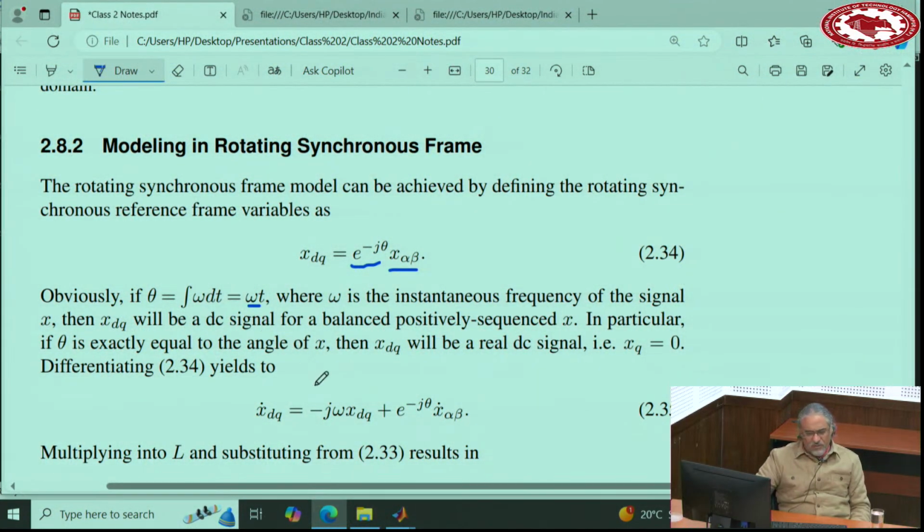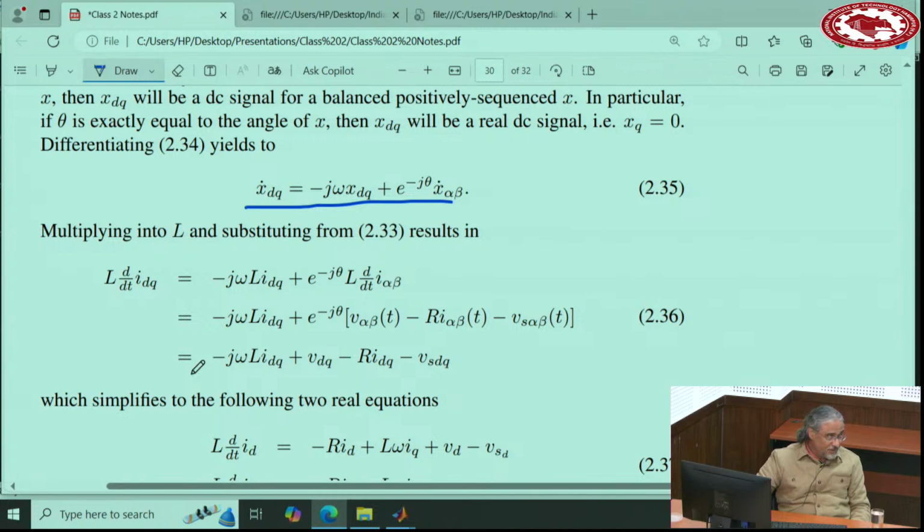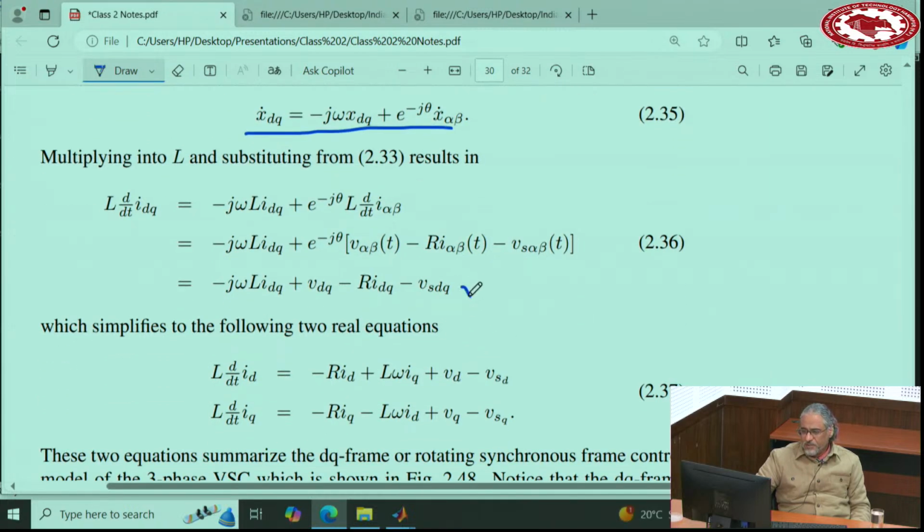However, the derivation of equations becomes a little more complicated because now you need to take the derivative of this equation and then go back and derive the equations. Do it when you get home or in your room tonight. And then we derive two equations. You can represent them here as one single equation or two separate equations. We call them D and Q for these new directions. Both of them are not rotating anymore, so XD and XQ, or ID and IQ.